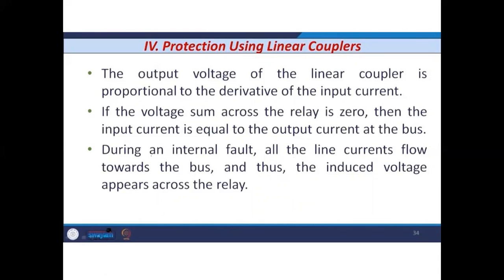The linear coupler is a special device and it can be effectively used when the CT saturation phenomenon is predominant. However, this type of scheme requires additional equipment to realize the benefit of the digital relay. That increases the overall cost of the scheme.